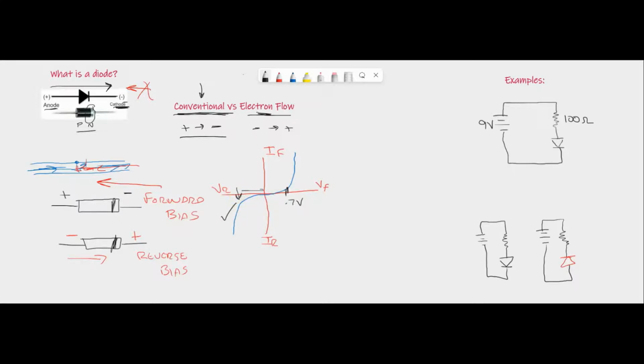But this is how it protects it. So in this section from like here to here, we're protecting that diode against anything that's trying to flow through it. In other words, the diode is off. But if that current or that voltage gets too high, then this breaks down. This is called the breakdown point, and it starts conducting the opposite direction, which is not what we want. These charts are found in any specification. You can look those up and see what those values are for any given specification.